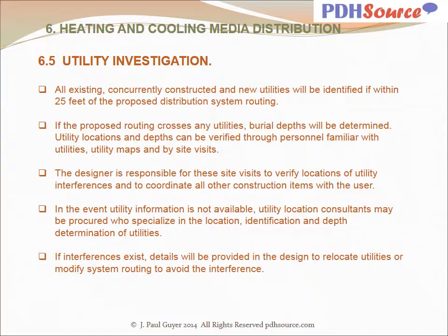The designer is responsible for these site visits to verify locations of utility interferences and to coordinate all other construction items with the user. In the event utility information is not available, utility location consultants may be procured who specialize in the location identification and depth determination of utilities. If interference exists, details will be provided in the design to relocate utilities or modify system routing to avoid the interference.